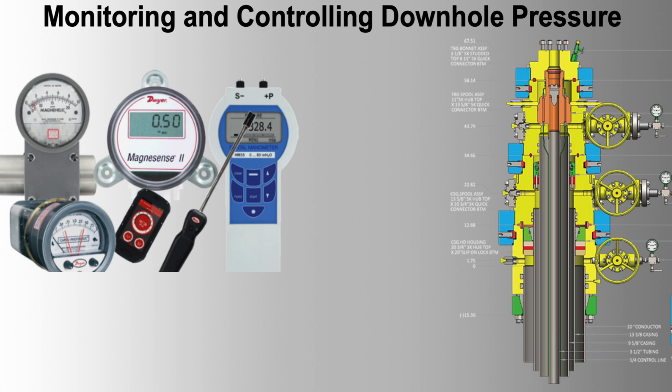4. Issue: corrosion of downhole instruments. Problem: corrosion of pressure sensors leading to inaccurate readings and potential failure. Solution: replace sensors with models made from high-grade corrosion-resistant materials like Inconel or Hastelloy. Implement chemical treatment programs to reduce corrosive elements in the well.